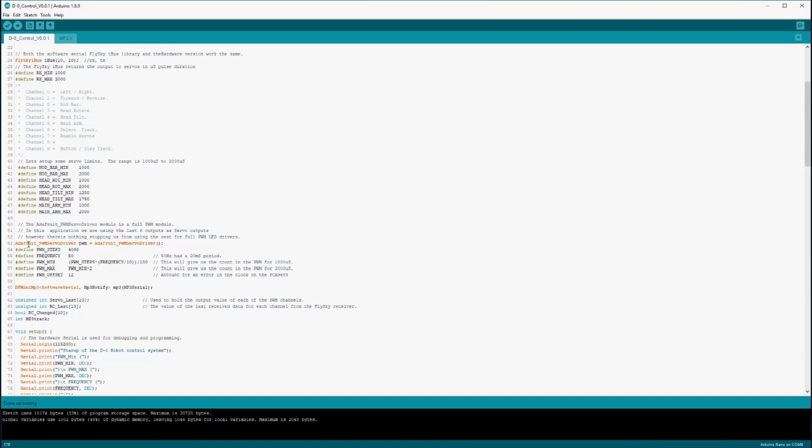Now, one thing I did discover while reading through the data sheets and by trial and error is that there is a turn on and a turn off time for the outputs. And in this case, setting an offset of 12 from the calculated values actually corrects my offset, and it actually zeroes all of the servos, which is quite handy. I've made this adjustable because it's working off the internal oscillator, and I think that's part of the issue, and it may need to be adjusted for your own particular build.